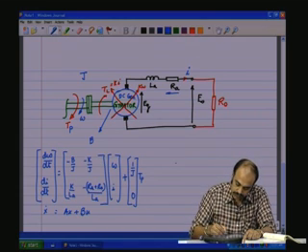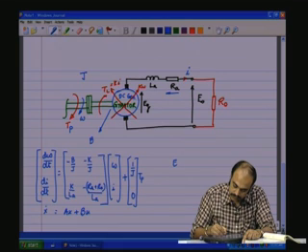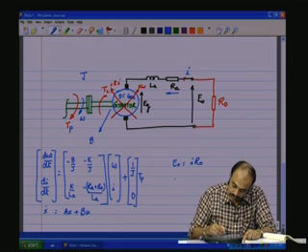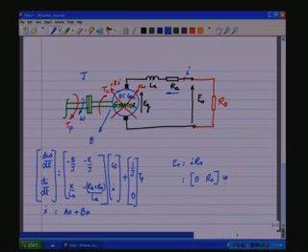Tp is the input, and of course, we could have an output equation, let us say E naught. Now, E naught is equal to i into R naught, which is equal to 0 R naught times the state vector omega i, plus 0 into Tp, that is y equals Cx plus Du. So, this forms the state equation representation of the DC generator, the mathematical representation of the DC generator in state equation form, and this is the dynamic model. As we said, in the steady state model, LA will vanish and we just have the resistive drop which comes into the picture.